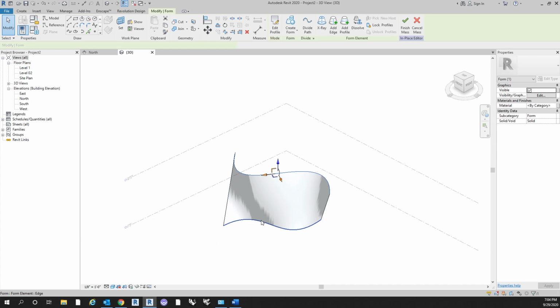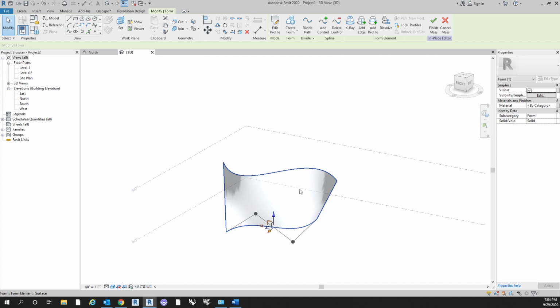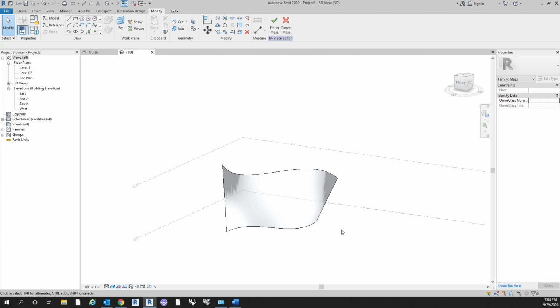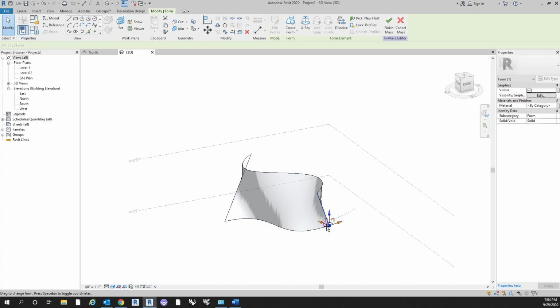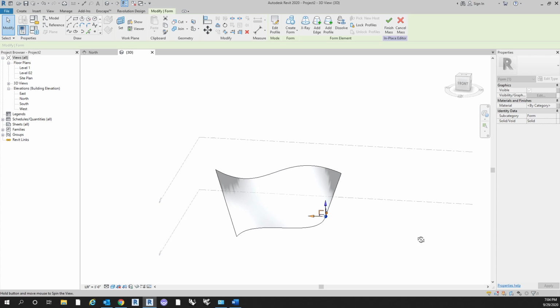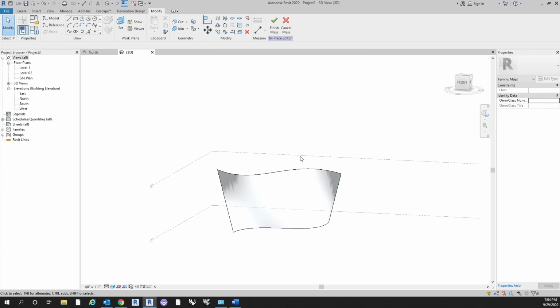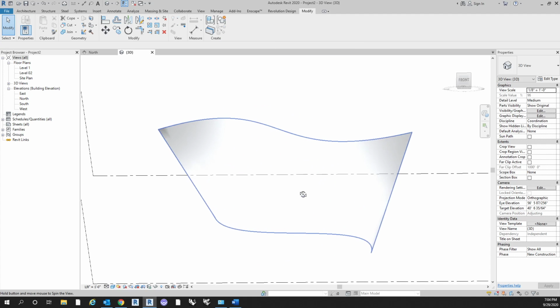But when you do that, oh, this spline actually kept its... oh, it's because it was spline 3 points. All right, so we have it, manipulate it however you want. Get it to be nice and double curved. And then once you're done manipulating it, hit finish mask. Now we have a double curved surface.